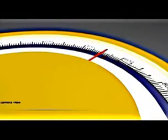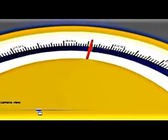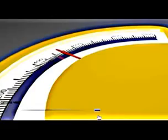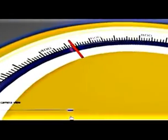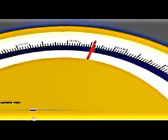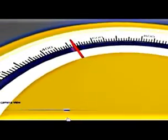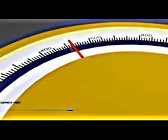When a pointer moves over a scale, the apparent scale reading changes depending on the position of the eye. If the observed reading differs from the correct reading because of the position of the eye, it is called a parallax error. For a correct observation, the eye should be vertically above the pointer.